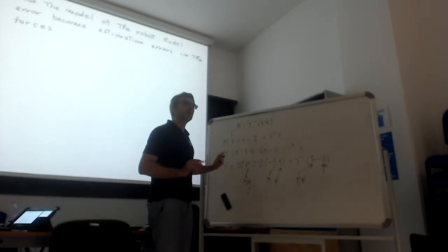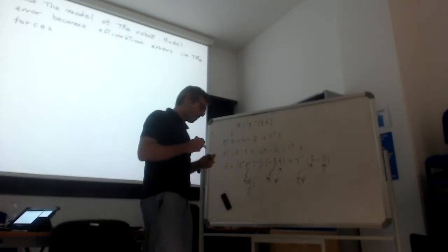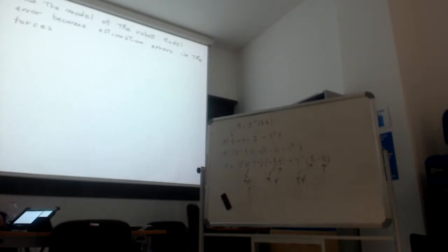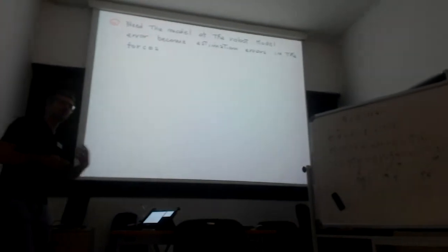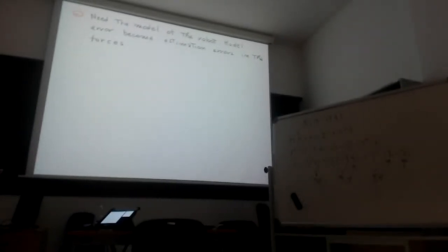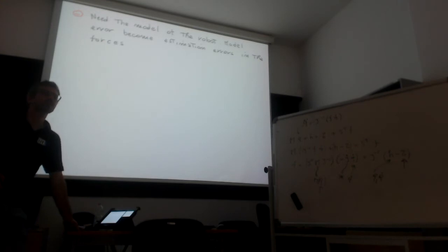And we can estimate the contact forces without having to use a contact sensor, a force sensor at the end effector, because whenever a legged robot is walking, the impacts are very high. And if you think about putting an ATI 6-axis force sensor in a robot that weighs 100 kilos, you will break it soon. So, in the absence of torque sensors, could we replace tau with computed torques or something like that, just using the model information? In the absence of joint torque sensors.